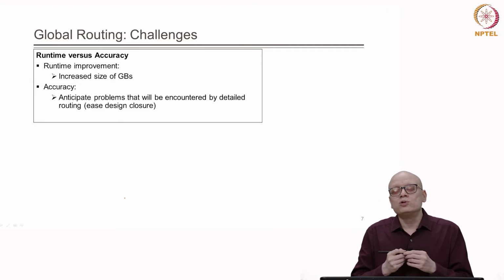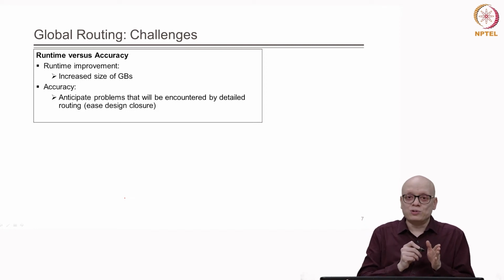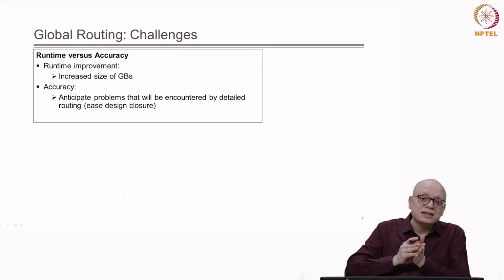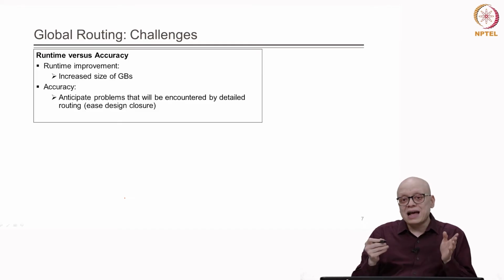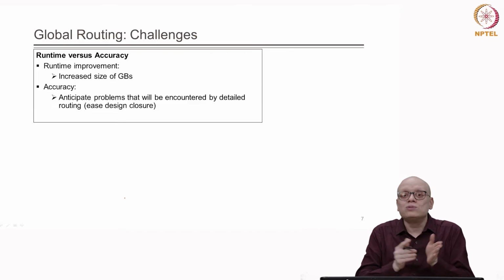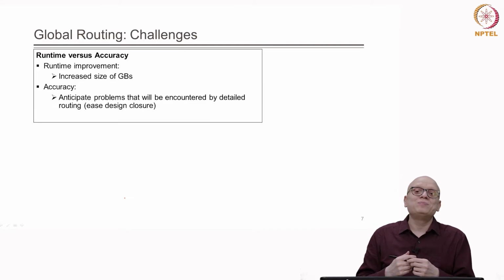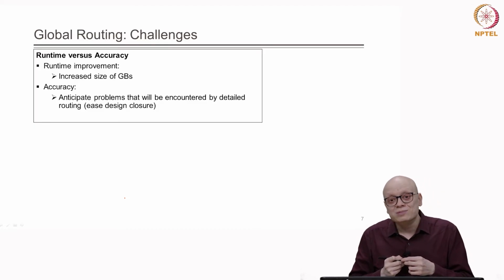For example, suppose the detailed routing problem is much more difficult than the global routing problem, and therefore the runtime of the detailed router is significantly higher than global routing. It may happen that when we run detailed routing, it takes, say, 12 hours to run, and at the end of 12 hours the detailed router simply says that it could not find a feasible solution.